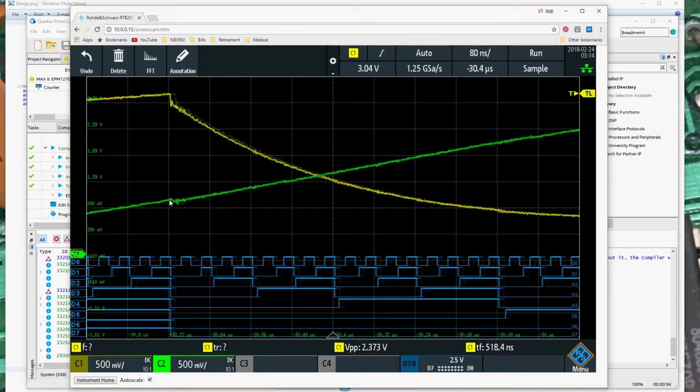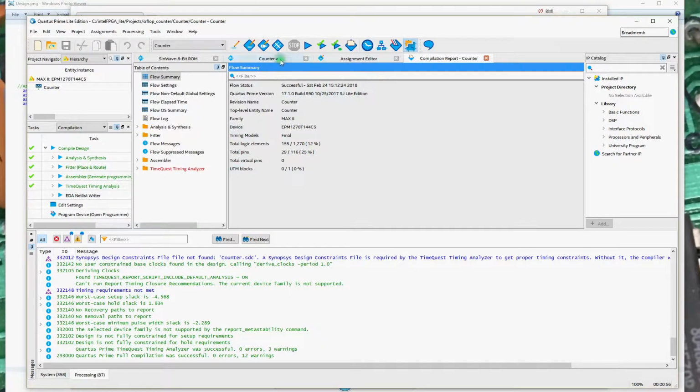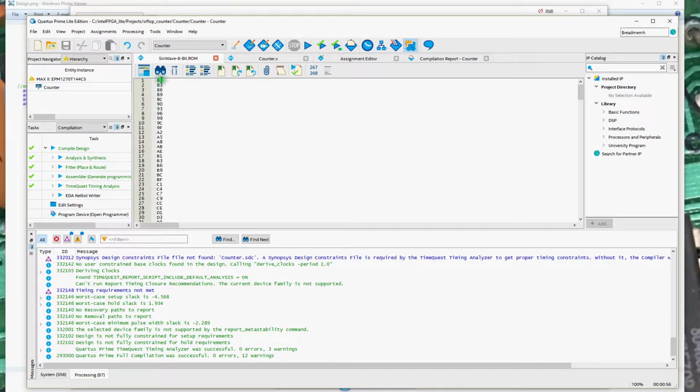In the ROM code, however, that's interesting. So again, it's nonlinear, the output here. It's not as clean as it could be. That should be shifting from all ones to all zeros. If we go back and look in the ROM, all ones would be outputting a value of 7D. When it switches to all zeros, that's outputting a value of 80 as it rolls around here.